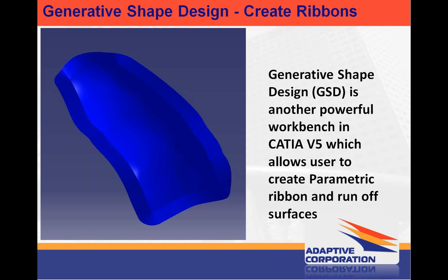So there's a few bits of the final manufacturing process that are basically being simulated within CATIA. Again, depending on the process that you're working in or the type of material you're working with, if you're doing a reverse engineering of an injection molded part, there's other workbenches that allow for quick, easy, and fully manufacturable parts, like the functional molded part and the composite design workbench. So it's based off of what the individual company or corporation or person is looking to do as well.